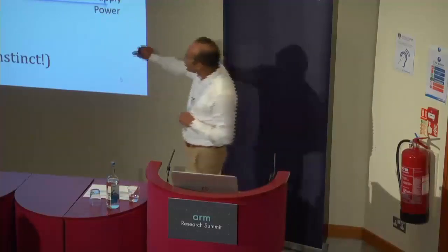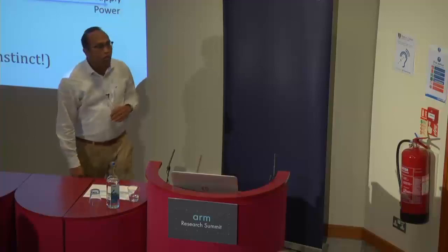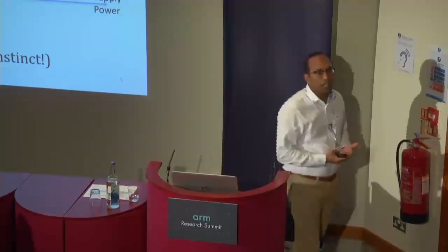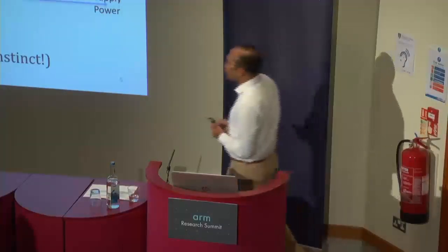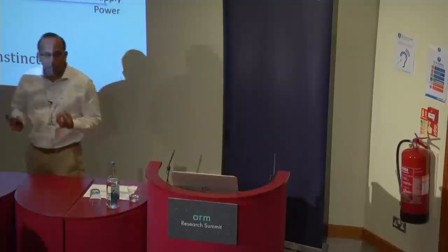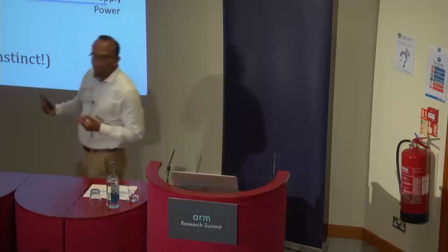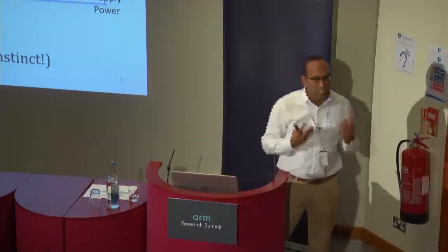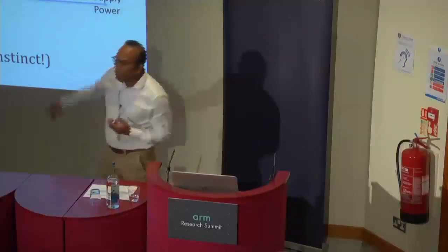And of course, there is also a continuing challenge, which is survivability at zero cost. Today, survivability or retention is initiated by something called dynamic retention. If you look at typical examples of retention, you're looking at roughly 3 milliseconds of sleep time before you go to sleep, and then another 3 milliseconds to wake up again. So you're losing 6 milliseconds of compute time because you do not have zero-cost survivability.